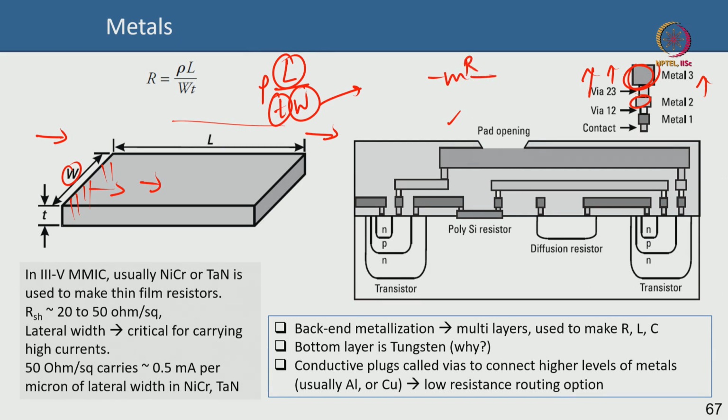Although I told you that in Smith chart impedance matching, you try to avoid resistive lines, you only go along the capacitive or the inductive lines, don't get me wrong, resistors are very critical in many aspects. You need to put a resistor, for instance, to intentionally reduce the gain of a device. Why do you do that? So that your device becomes stable. That's just an example. So resistors are very critical, by the way.